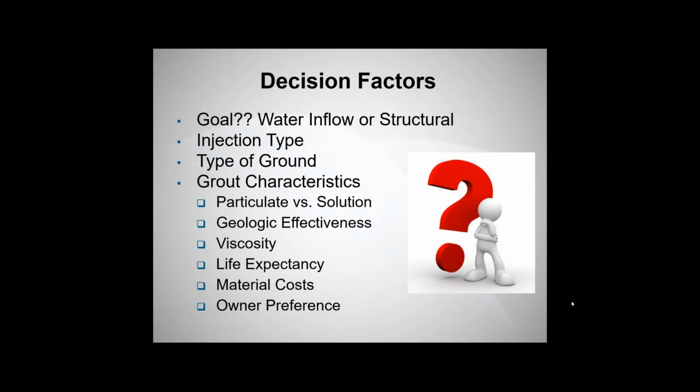The injection type really comes down to the type of ground. So you've got to understand the geology. The geology dictates the grouting. It is the most important thing. If you don't understand the geology, you'll never get the grouting right. Once you understand the geology, you can understand your injection type, whether that's going to be consolidation grouting or permeation grouting. Again, previous webinars we've done, other types we haven't talked about yet.